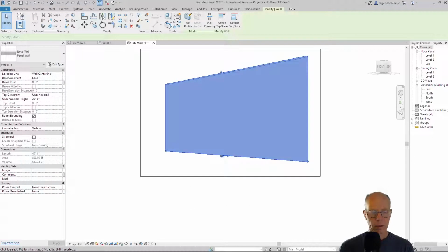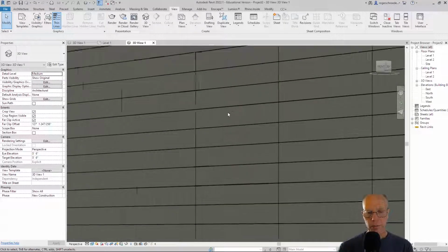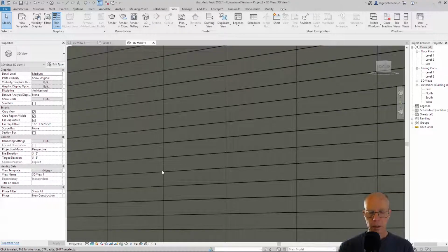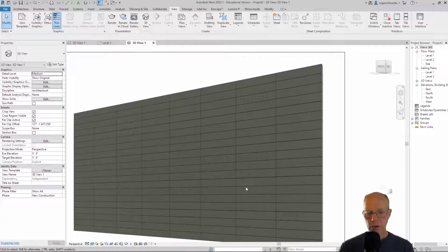We'll go ahead now, and we will render that in a realistic mode. And now we have a tiled wall system. And you'll see when we zoom in here, the horizontal joint is a little narrower towards the other one. I see this is a little disturbing because it isn't always continuous all the way across. So I might make adjustments to that, to get it to look more even or pleasant to you. But I will now leave this part of the clip, and the next thing we'll pick up with is the idea of placing a window system within this grid.